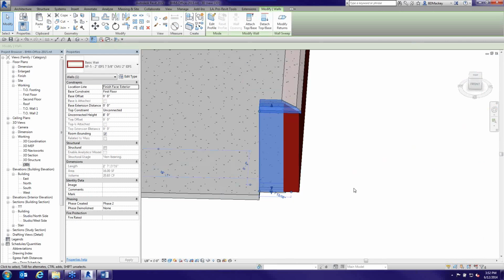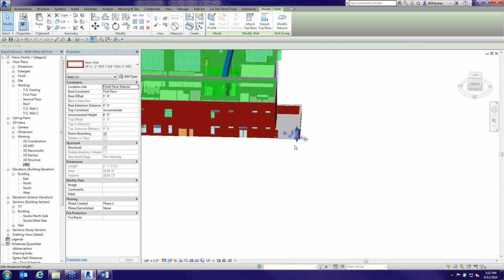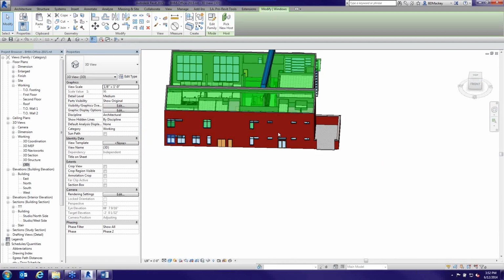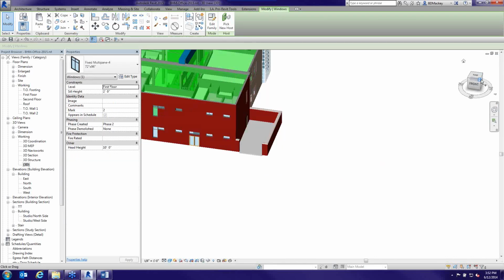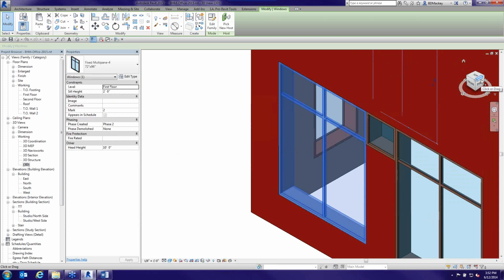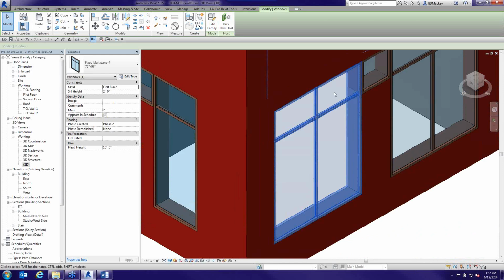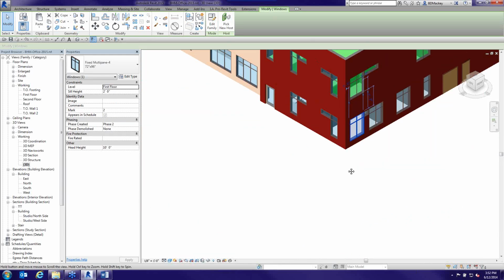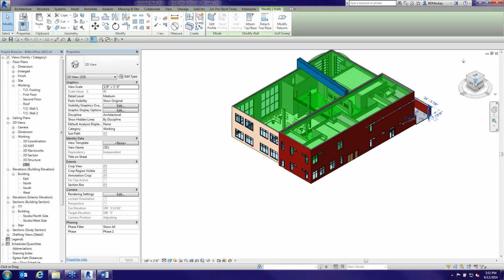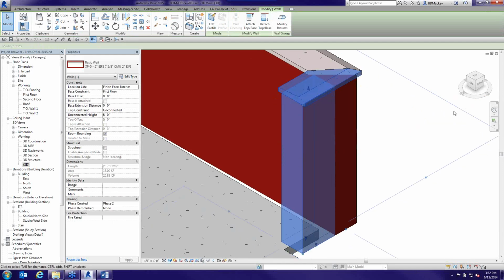The other thing is if you do pick an object, I can then click on the view cube, and the view cube zooms me into that object. So if I pick an object and then use the view cube, not only does the view cube rotate around that object, but it'll zoom you into it. Like, oh man, I need to go look at that wall. Boom, takes me right into that wall and zooms it into the center. So knowing that you have that with the view cube and the 3D views becomes pretty handy when you're getting into using it.